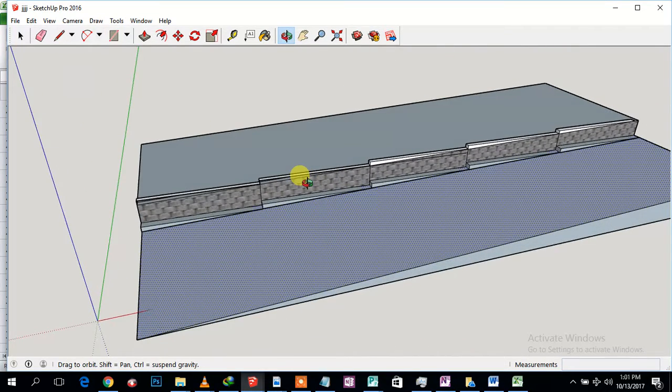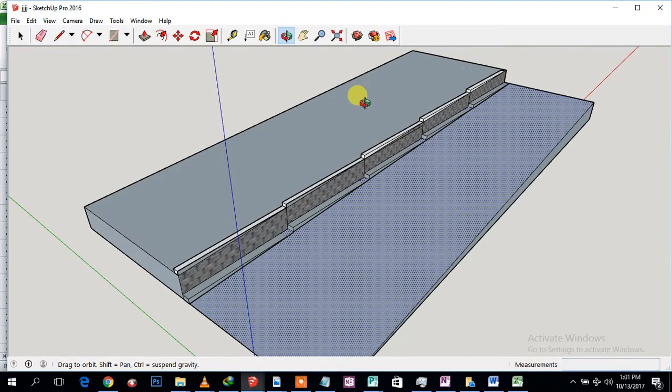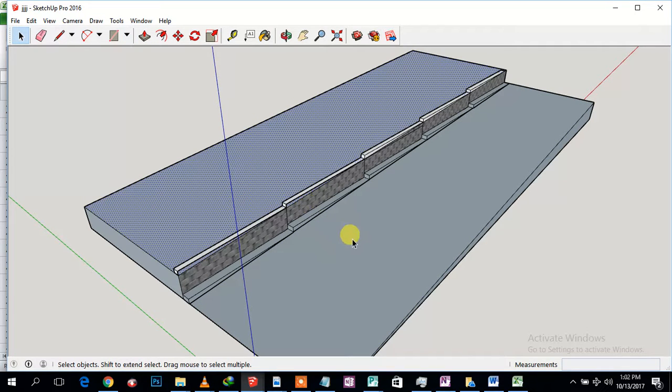Okay, so basically, we've got two levels. Number 9 is relatively higher, and number 7 is relatively lower. So that's why there is this problem along the boundary line that is getting pushed over by sand. So what you're going to need to do is a slight excavation. We're going to expose and disassemble everything, then do a little bit of excavation, and then build up a small retaining wall to hold this bank from number 9, right? And we retain that to make sure that no matter what happens in future, it won't push the boundary fence again.